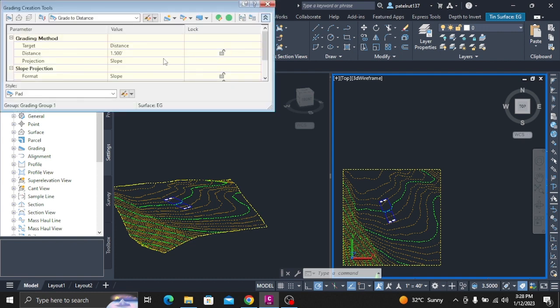Click Home tab, Create Design panel, Feature line drop-down, Create feature lines from objects. Click the polyline between circles A, B, and C, press Enter. In the Create Feature Lines dialog box, under Site Name, make sure that Grading Building Pad is selected. Under Conversion Options, make sure that the Erase Existing Entities and Assign Elevations checkboxes are selected.